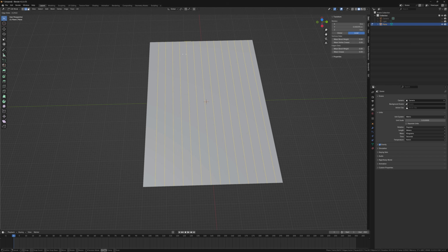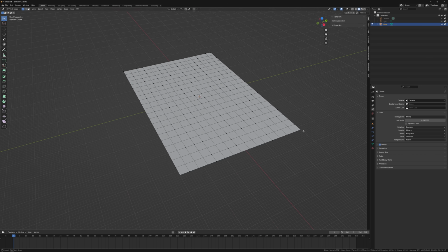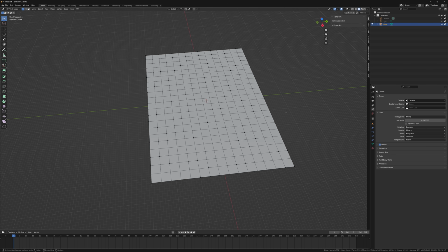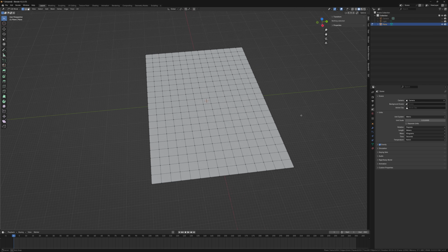Just don't do anything. So I right click now, then it goes to the default, or you can just hit enter twice before moving your mouse and you're good. And in the opposite direction, because we need 21 rows, we need 20 cuts. So Ctrl R again, put the mouse on the right axis, hit 20, enter, enter, and you're done. There's your basic grid. Now, if you want a hex grid or something else, that's a little bit more complex, and I haven't worked that one out yet, but that's something I have in mind for possibly a future project.